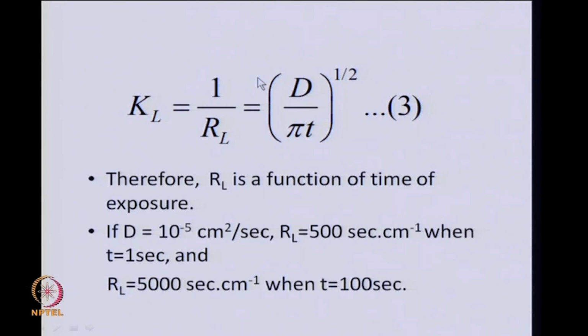And this is the main difference between these renewal models, dependence of K L on diffusivity, which is different from the other models. In film model, we should expect K L proportional to D, okay? And in the boundary layer theory applications, we will have diffusivity to the power 2 by 3. Those are typical other important models, and in experiment, this is the best agreement because it is somewhere in between the whole range of exponents we see on diffusivity, 0 to about 0.8 or 0.9.